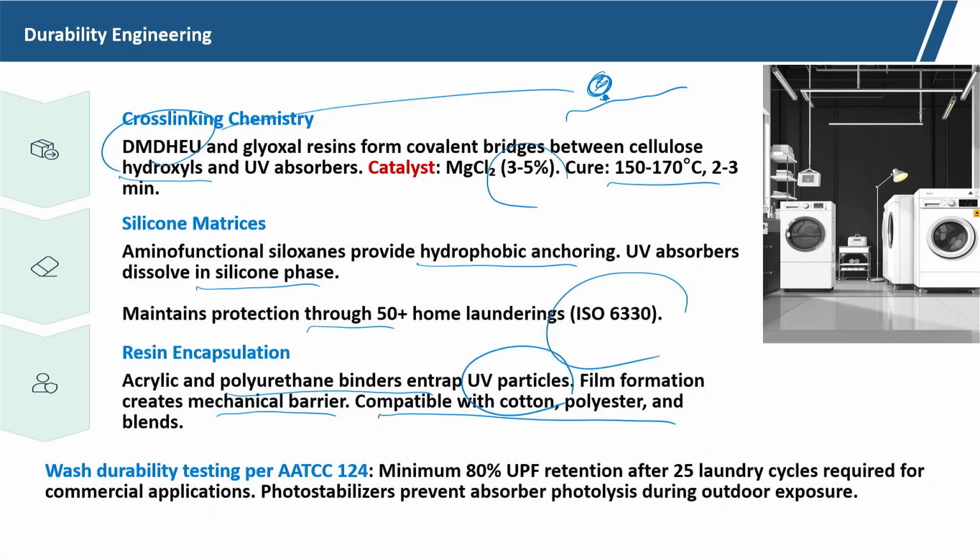And after all this durability engineering, we can test the durability by the AATCC 124 method. A minimum of 80% UPF retention after 25 laundry cycles is required for commercial application. So, at least 80% UPF retention should be there,